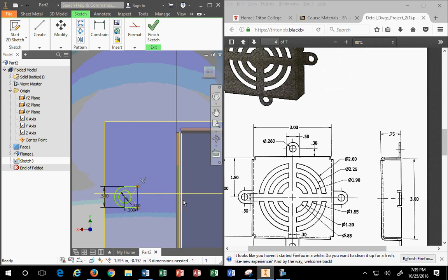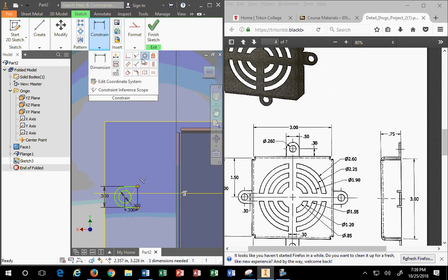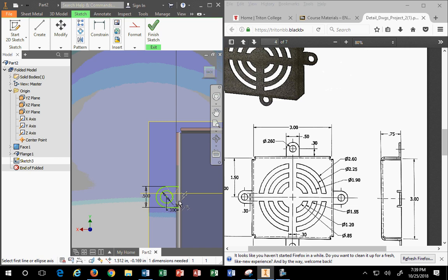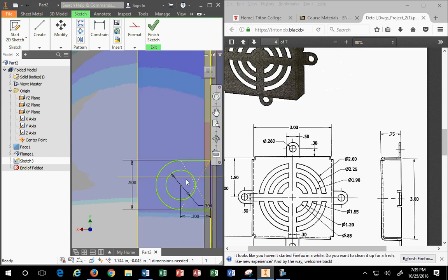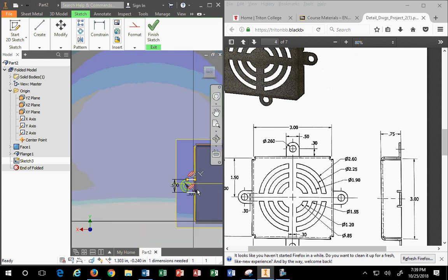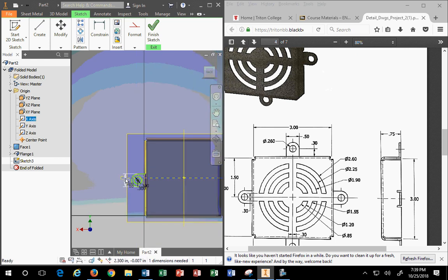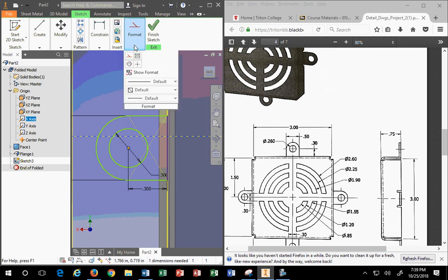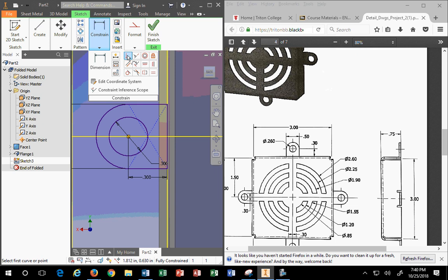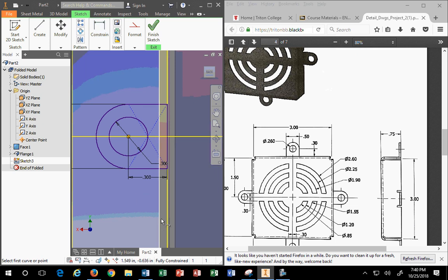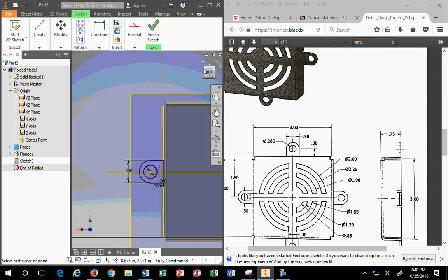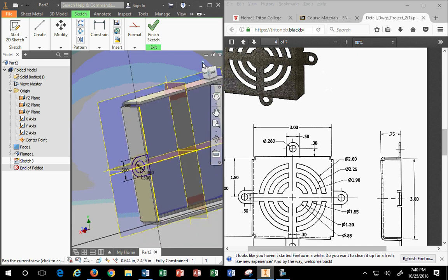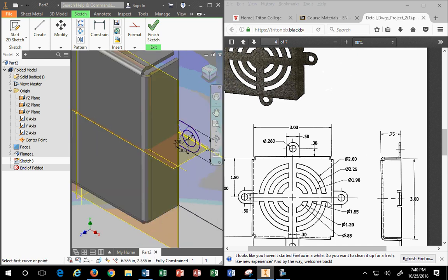This needs to be attached to this back wall. So they need to be collinear. So that, all the usual stuff. That's the stuff you know how to do on your own. That's why I just did it. It's not centered. So what I can do is take this plane, take this center, make it coincident. Okay? That's the position of that tab, I'll call it.